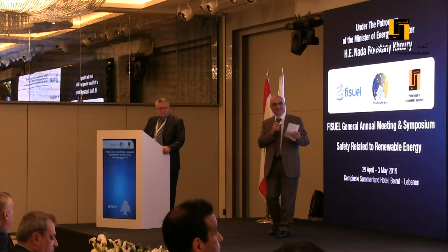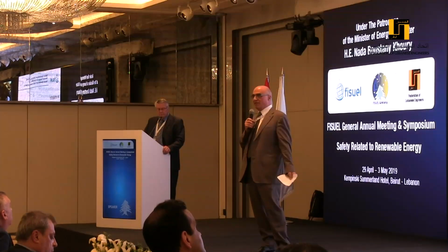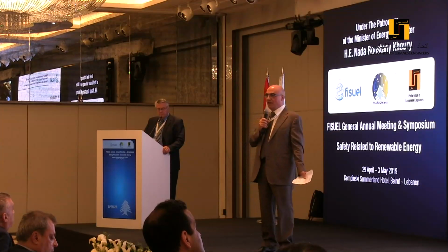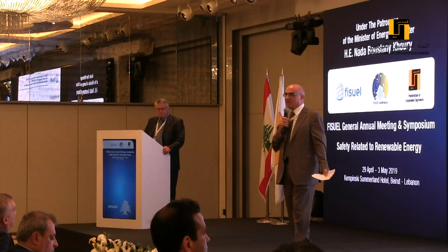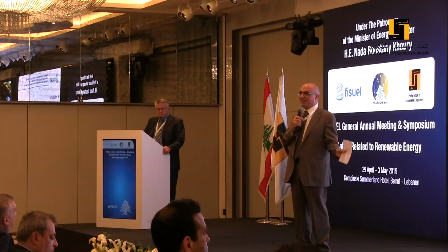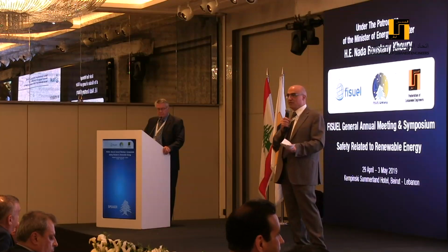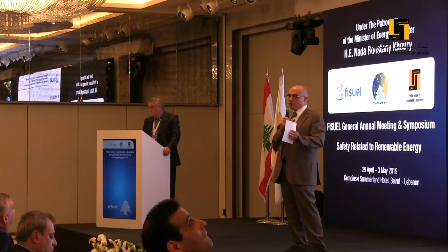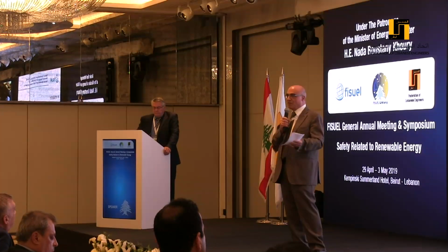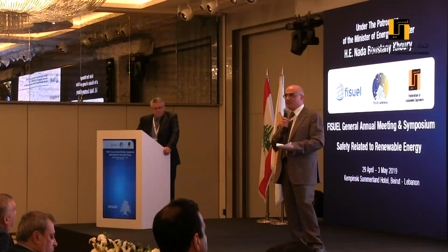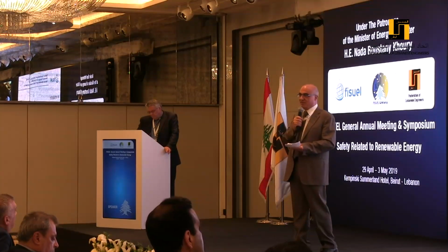Regarding the standards, whenever there is any new invention in the elevators, you have 10 years of patents, and they will not be covered by any standards. They will be covered by the EU type examination certificate for this specific type of lifts. Exactly what happened with Kone when they invented the machine roomless in 1994: until the year 2004, EN 81-1 mandated to have a machine room. Kone and several other companies after that were installing the lifts based on the EU directive and the EU type examination certificate.